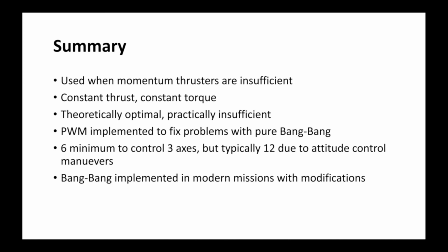to utilize constant thrust and constant torque in your spacecraft. Bang-bang thrusters are theoretically optimal, but practically insufficient compared to other propulsion methods. However, pulse-width modulation can be used to help fix the problems with a pure bang-bang system.